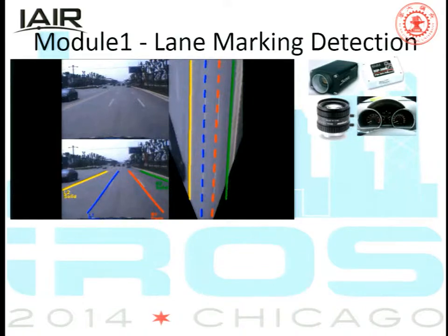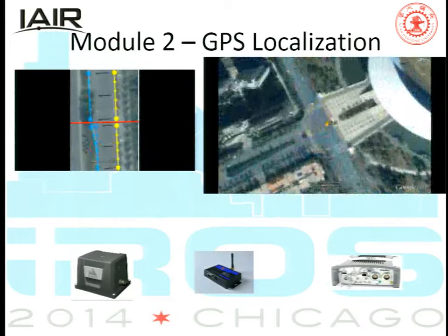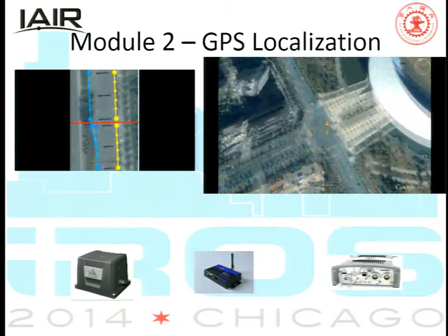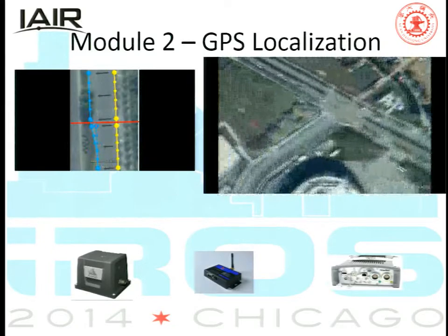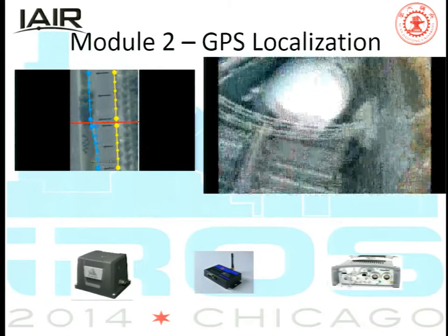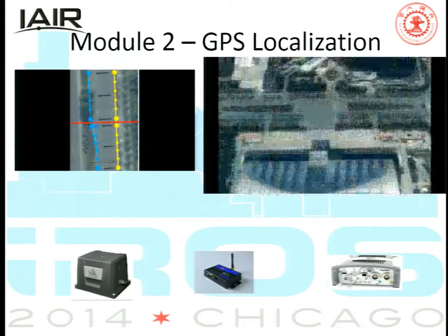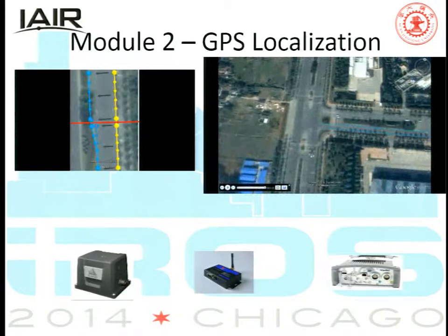A high-accuracy lane boundary map is also built offline as a digital map made by a set of points. Each point contains the global position of the leftmost boundary and the rightmost boundary of the road. All these positions are collected by an intelligent vehicle equipped with GPS and are corrected by a semi-automated method. This ensures high accuracy up to centimeter level in the map. A sequence of these points constitutes the description of the road shape.